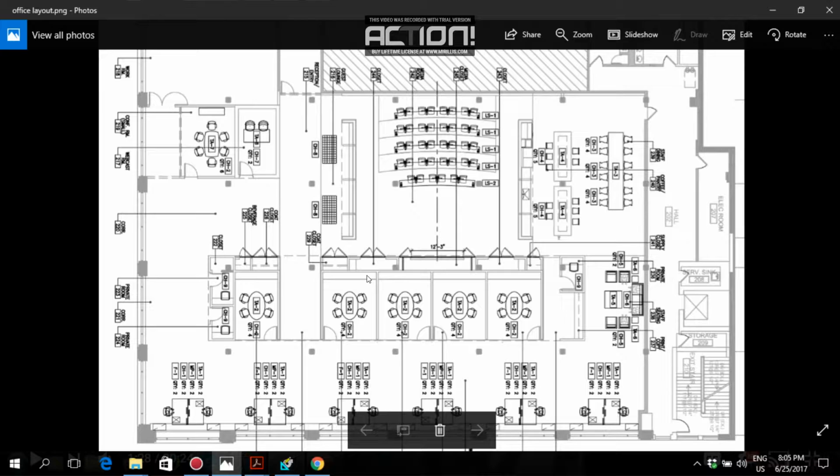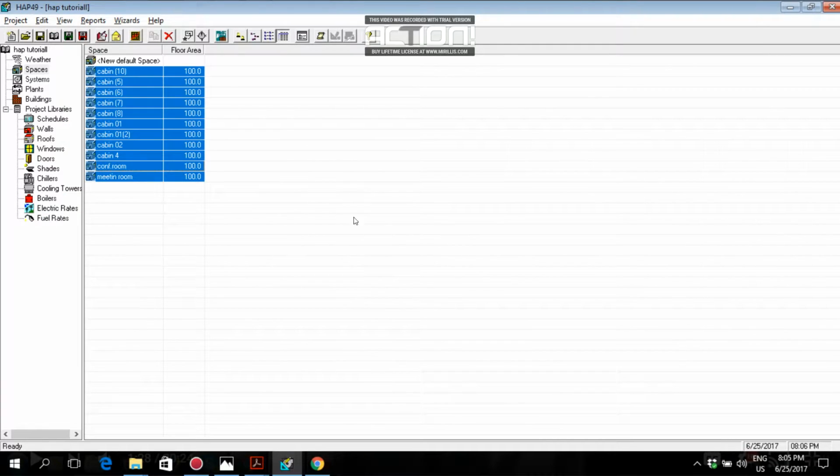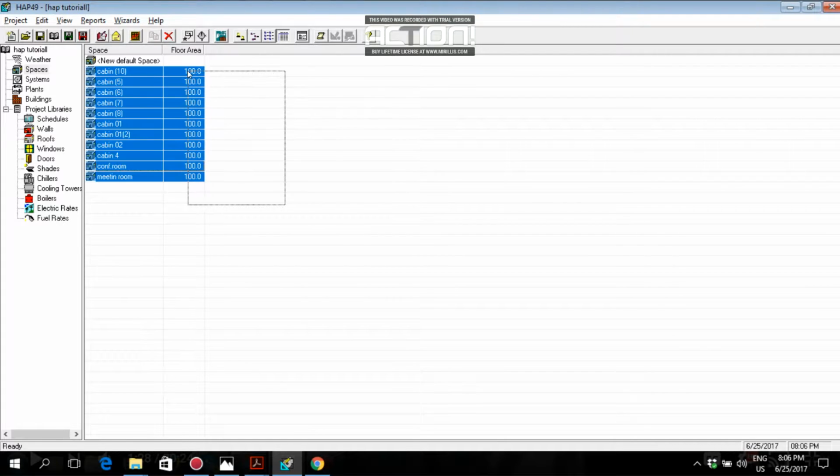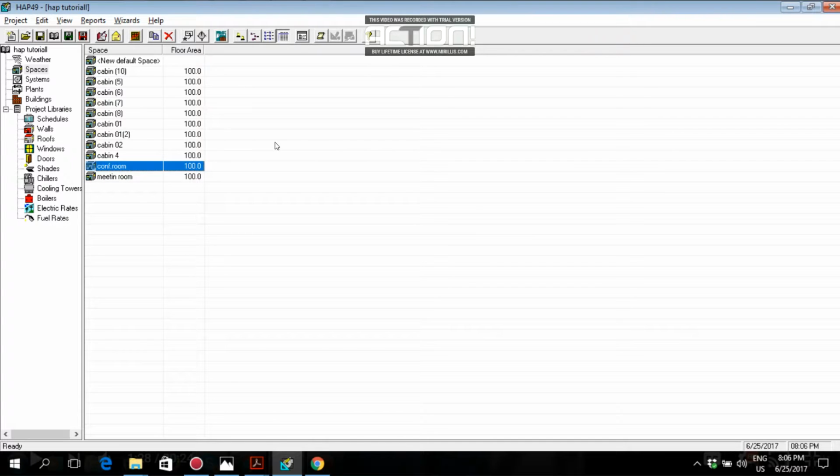When you say system, you have a chilled water system, and you have a DX system. In the chilled water system you will have air handling units and fan coil units, if you are already aware of these. In the DX system we have split units, package units, and window units. To make this example real world, we will consider a regular system which is used in huge projects, like a chilled water system. If we are considering the chilled water system, I'm going to consider an example of an air handling system.